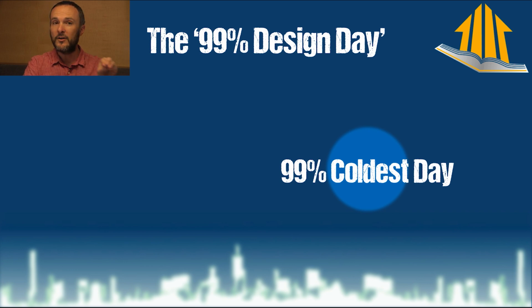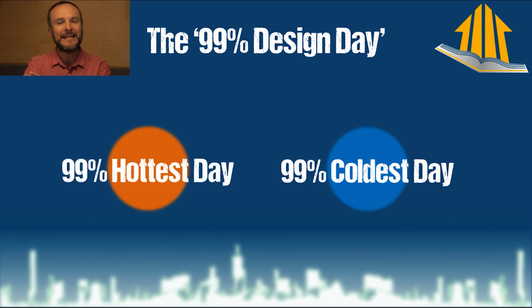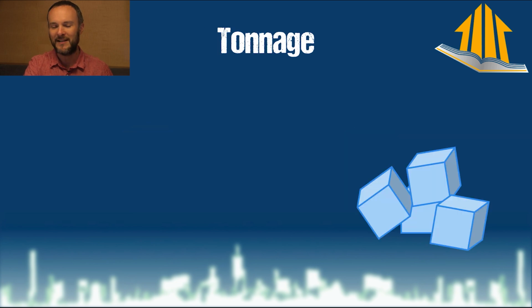You want to go to one of those two resources that I already mentioned, ASHRAE or Manual J, and you can find this information freely online. What is the 99% design day for your location? This is a big red flag generally. People use the 100% rule a lot, and that's one way that you can kind of game the system.